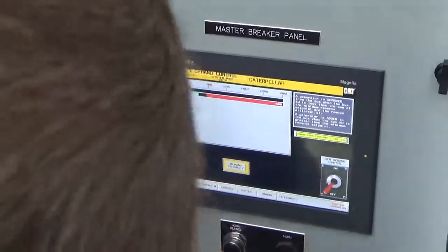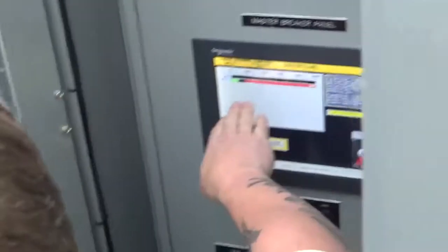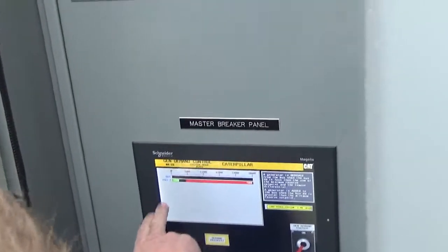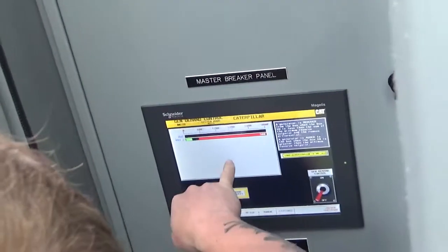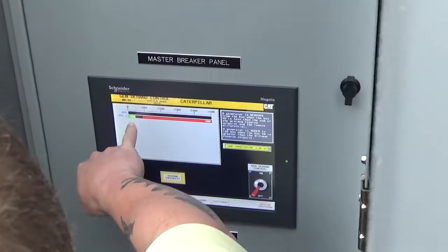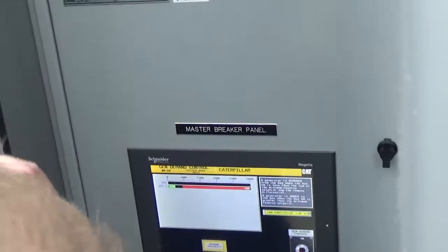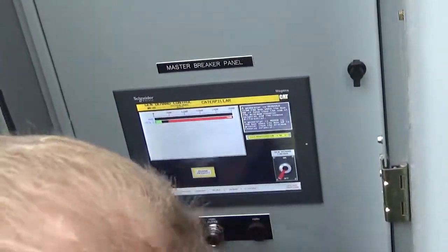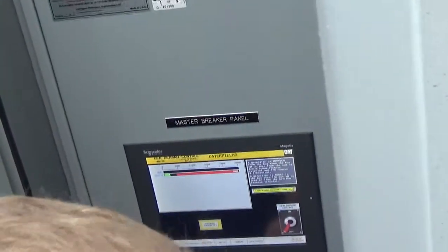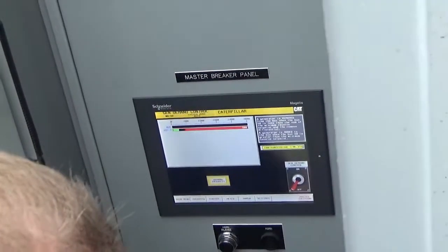So here, if you want to see, this shows a good graph of when it takes a gen off and when it adds one. So right now, if you only had 1 gen on the bus, 250 kW, if you were below 250 kW, it's going to drop a gen off the bus. Okay.